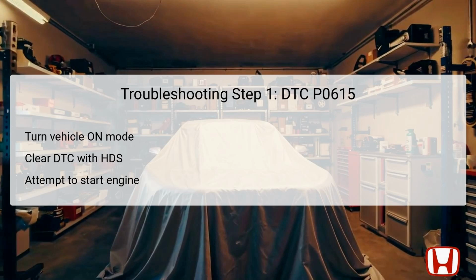Once cleared, attempt to start the engine to check if the code returns. Monitoring the HDS will help identify whether a pending or confirmed DTC arises after this attempt. It is essential after this phase to ensure all connections are properly secured to the PCM and the relay circuit board, as any intermittent failures may not show up during initial checks.